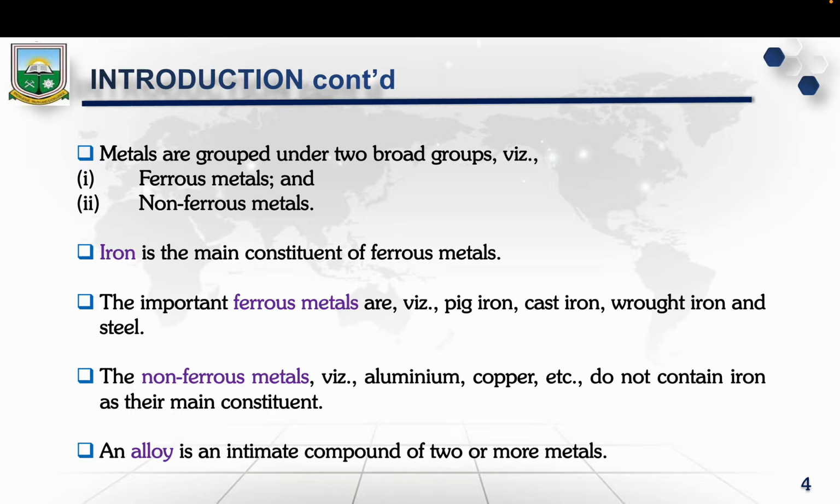Now, why is this distinction between ferrous and non-ferrous metals important? In general engineering, the choice between a ferrous and a non-ferrous metal can affect everything you are doing, from the weight of the structure you are trying to erect to its resistance to environmental factors like corrosion. For instance, steel, which we know from iron rods, is a ferrous metal, and one thing steel is known for is its strength. Aluminum, which is a non-ferrous metal, is chosen in applications where weight reduction is key.